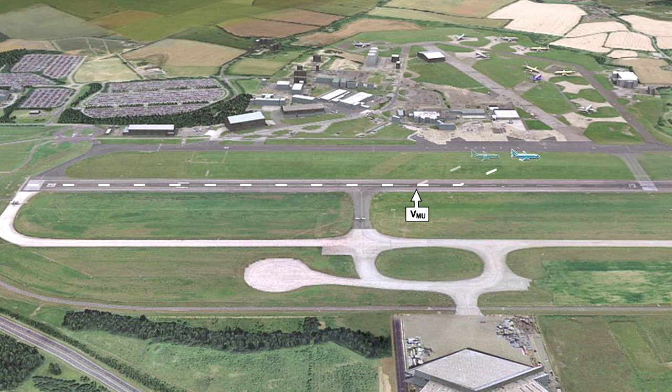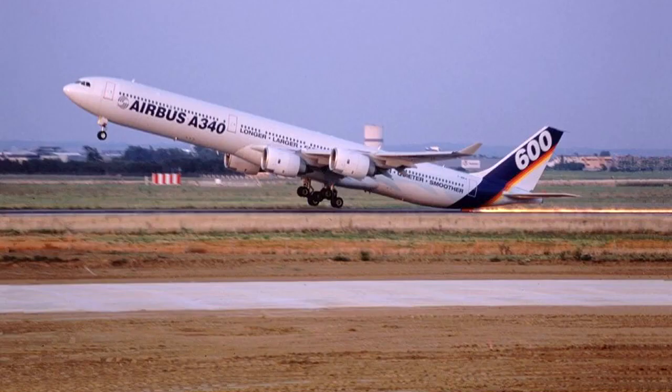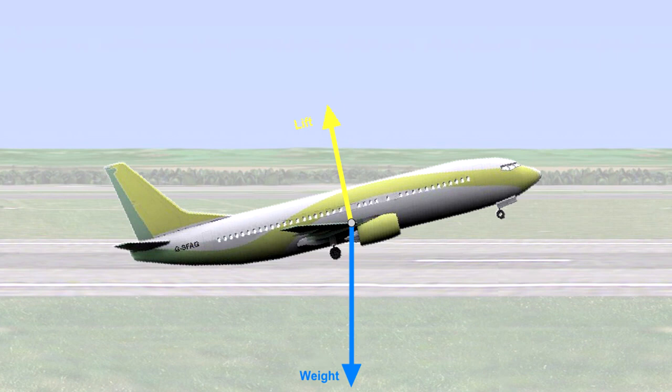The reason is because Vmu is very close to the stall speed, and the aeroplane controllability is very sloppy. And lastly, in order to actually lift off at Vmu, some fairly dramatic actions take place, which may be uncomfortable for the passengers, as shown by the image on the screen. It may seem strange, but the aeroplane is actually able to lift off at a speed where lift is less than weight. The reason being because so long as the nose can be raised to a high enough attitude, then there is a vertical component of thrust, which, together with lift, balances weight.